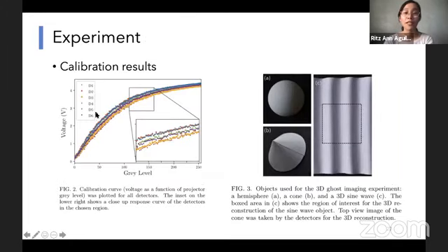For the calibration part, as you can see here, these are the calibration curves collected by our system for the 6 single pixel detectors. Even if they were manufactured in the same way, there are still discrepancies, which means they have differing sensitivities, and which tells us that the light magnitude collected by the LDRs may not be the same. And so we can use the semi-calibrated photometric stereo algorithm to solve this problem of differing sensitivities.